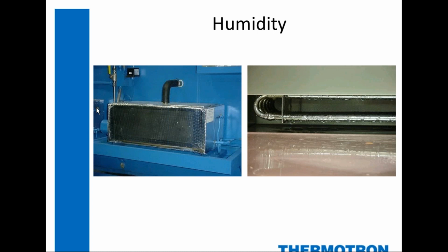So we will boil water in a device that looks like this. It has a heater submerged in water, and then that steam is produced and it's piped into the environmental chamber. And then when we want to reduce the humidity level, there's something inside called a dehumidify coil.